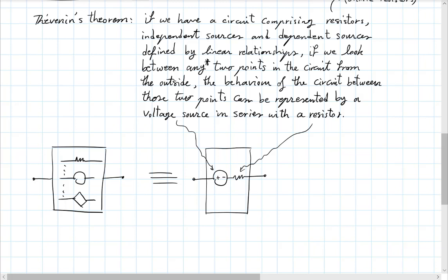We just already argued that one voltage source and one resistor can give you any straight line with a fixed slope, and shifted vertically. And then the other piece of the argument is, well, we have to argue that this big box, the original box with all these elements, in fact, we expect it to end up with just a straight line with some slope shifted somewhere, right? And that's really based on the linearity property of the whole circuit.